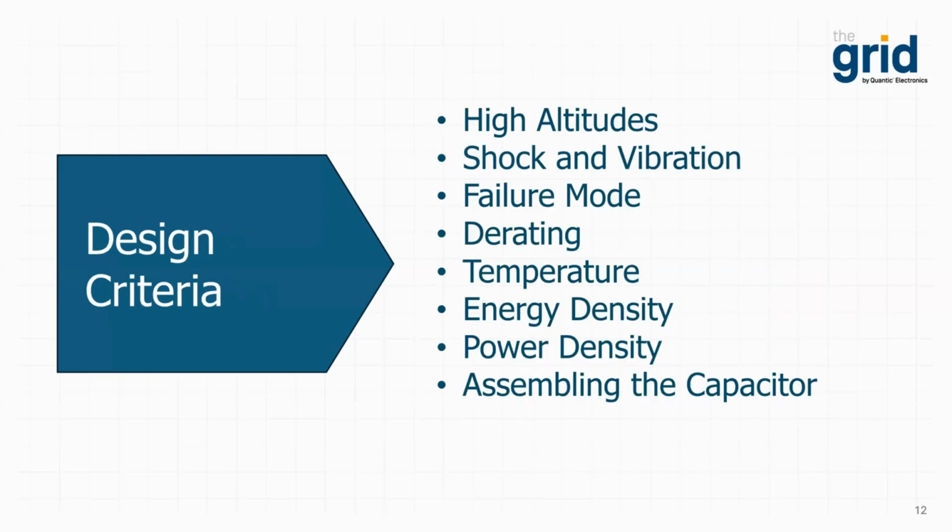When selecting the best capacitor for a unique avionics application, you will need to consider key critical design criteria, which include high altitude, shock and vibration, failure modes, derating, temperature, energy and power density, and assembling the capacitor. So let's take a closer look at the specifics of each of these criteria.